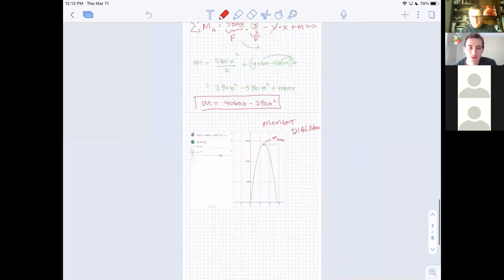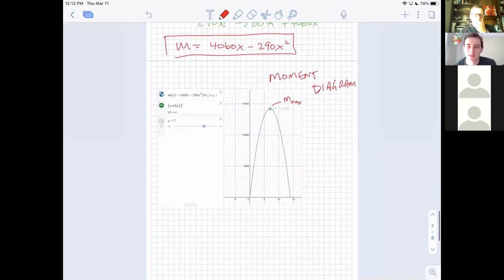So did we not look at the horizontal force because it was kind of the same plane of the beam? Well, there just wasn't any forces on it horizontally. Does that make sense? Oh yeah, so there wouldn't be any. So we could do that, but we just say there's none. In other words, the beam isn't going to have any forces pulling or pushing on it. Well, unless we come back and put an arrow pushing on it at an angle someplace, then we'd have one. But again, loads tend to be because of gravity, so you tend not to have too many horizontal loads unless you add one yourself. So that's a great question.